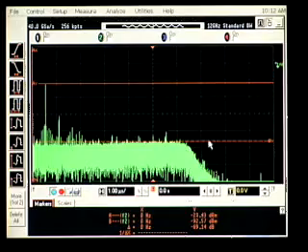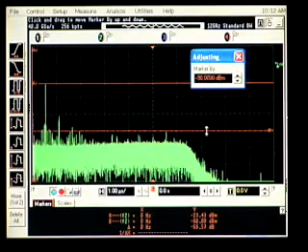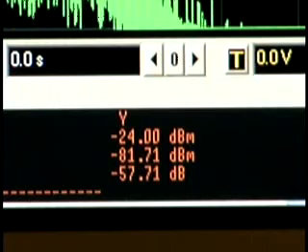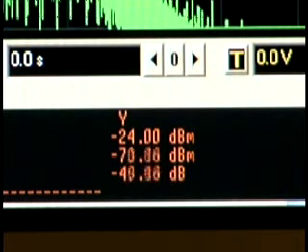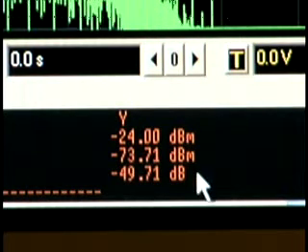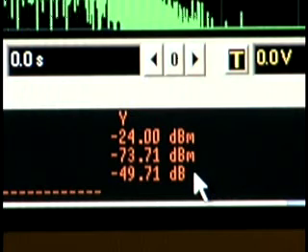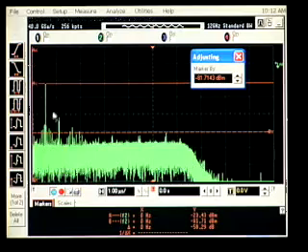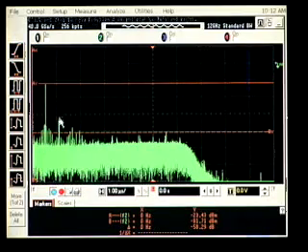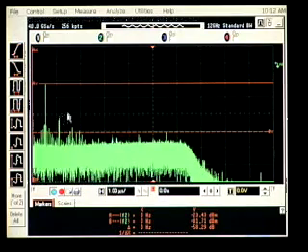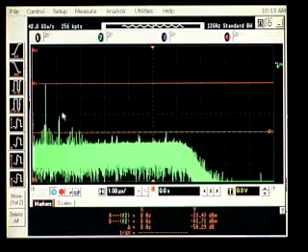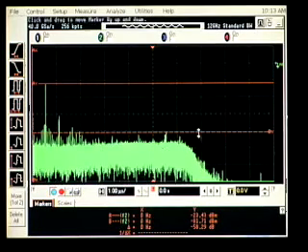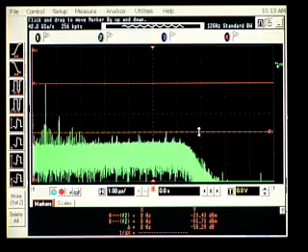Now we can move that cursor up and look at the range on these digitizing spikes, and you see those range from about minus 60 dB to about minus 50 dB. Now the spike right here at 2.2 gigahertz is the first harmonic of our 1.1 gigahertz tone, which is coming into the scope. So that is the dominant portion of the harmonic distortion.